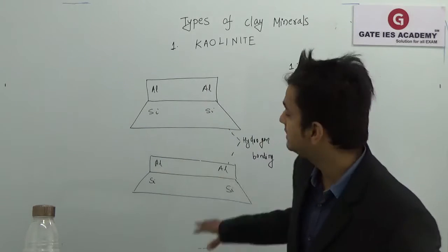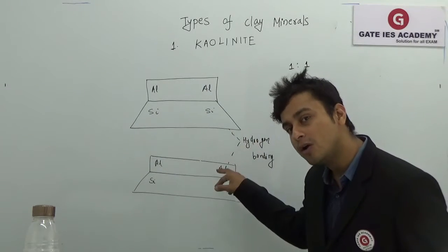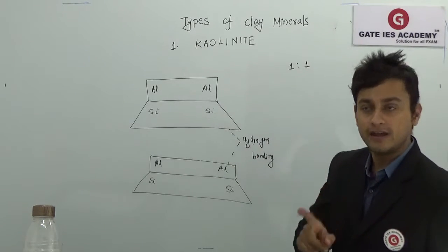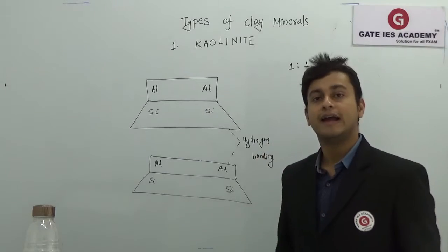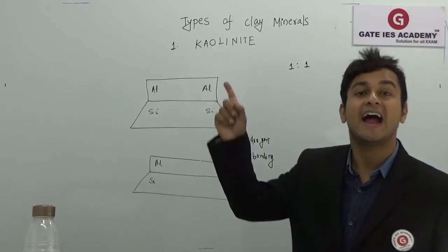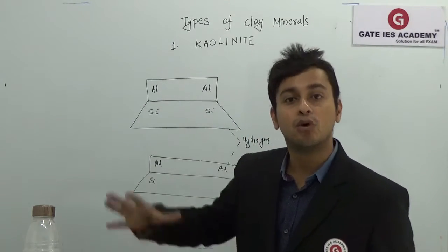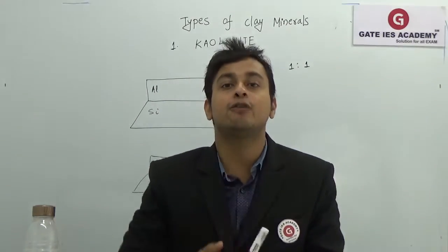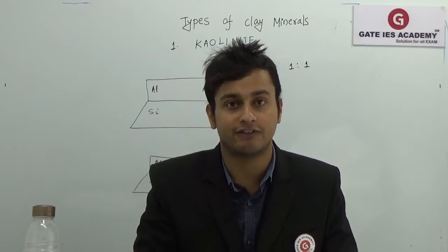So here its water content will be low, because the water cannot break the bond and get in the voids. So water content will be very low. It will be of low plasticity and a low active mineral. The more water it can take, the more it can swell, the more it can shrink. Therefore the soil is more active.